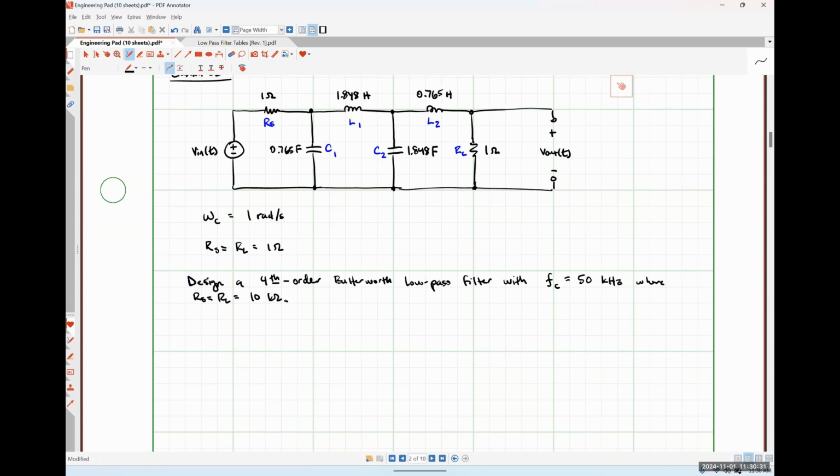So using literally just these two pieces of information, we should be able to figure out what our scaling coefficient for our magnitude scaling is, Km, and our frequency scaling, Kf, right? Kf should simply be our corner frequency or resonant frequency after scaling divided by our corner frequency or resonant frequency prior to scaling, okay?